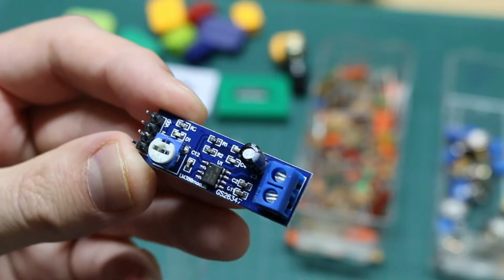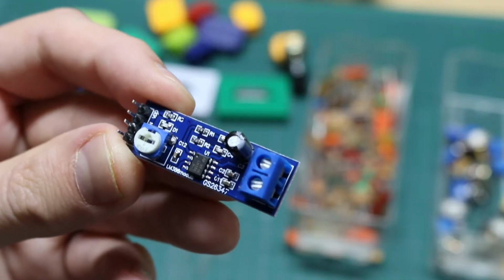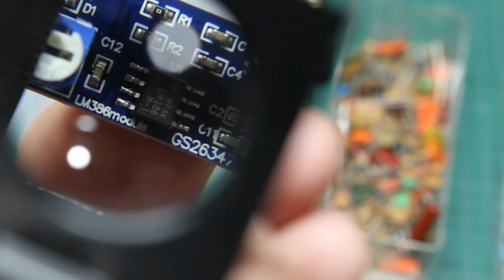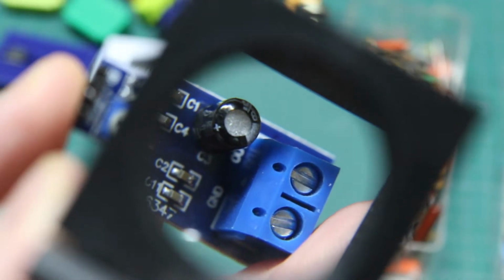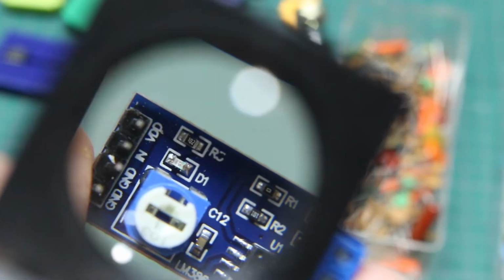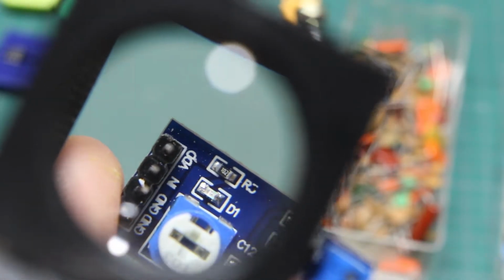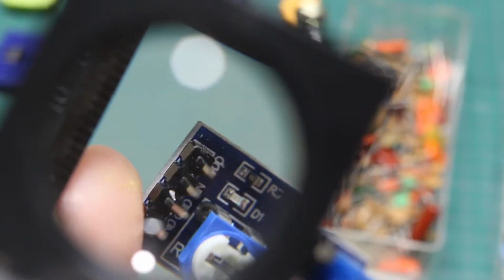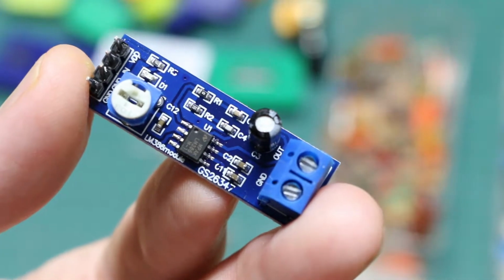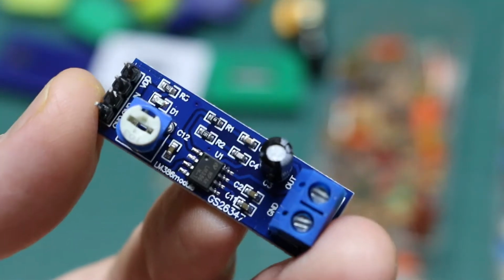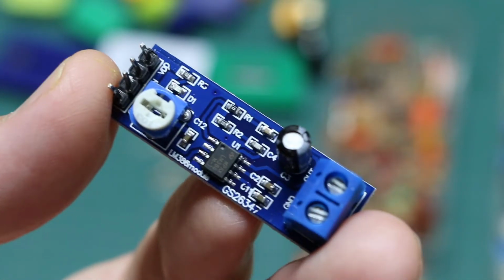Another thing I want to try using, this LM386 audio amplifier I've had for a long time and haven't used yet. So it's got an LM386 surface mount version, and of course output screw terminals for the speaker and a potentiometer for volume, I assume. And we have ground and VDD in and ground and audio in. So nice DuPont cables will help me out with this, and hopefully that will make it nice to hook everything up to a speaker and drive it properly instead of having to drive it from the output of an op-amp that may not be able to handle the load.